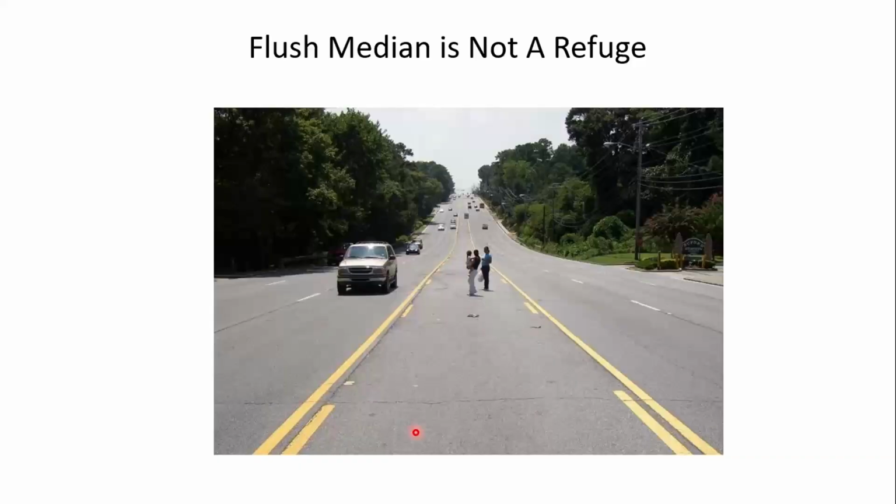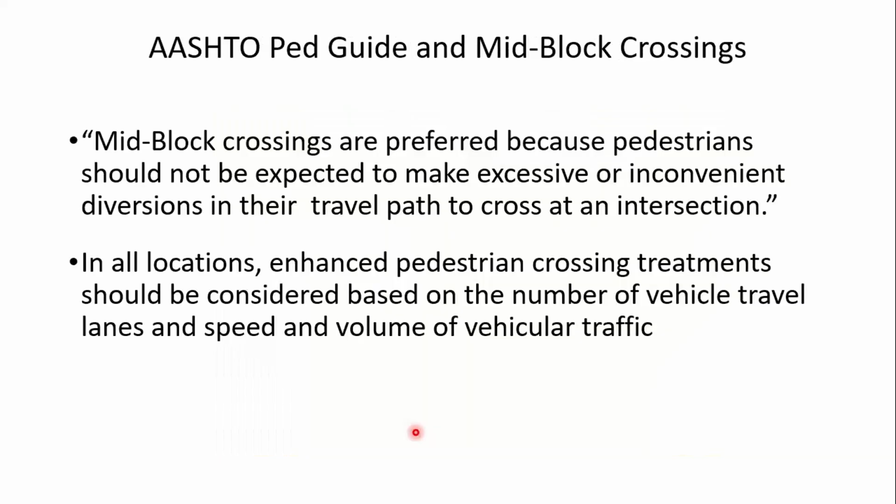They're in a two-way left turn lane, maybe on an arterial that has many driveways, and drivers turning in or out of the driveways are more focused on looking for gaps in traffic and the path to or from the driveway, and they don't see the pedestrians, and pedestrians get struck. So this is not a refuge area for pedestrians. We'll look at some treatments in a few minutes of what might be done.